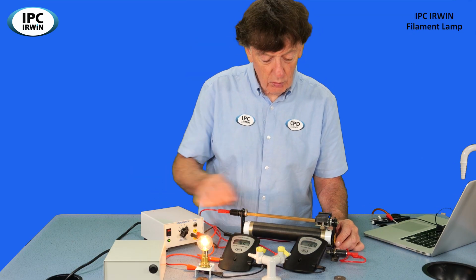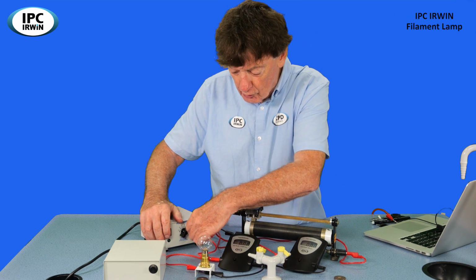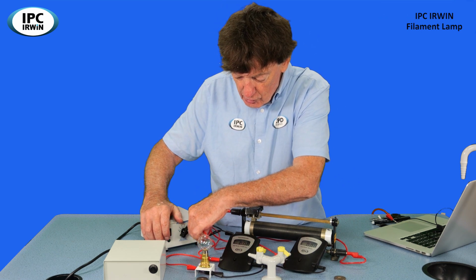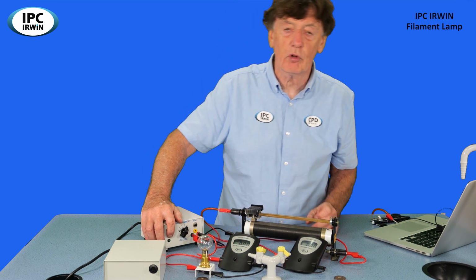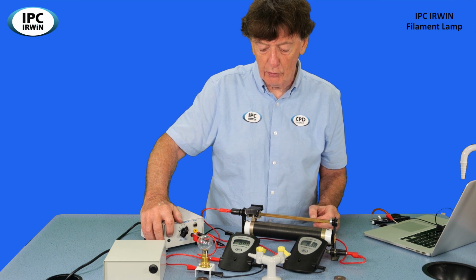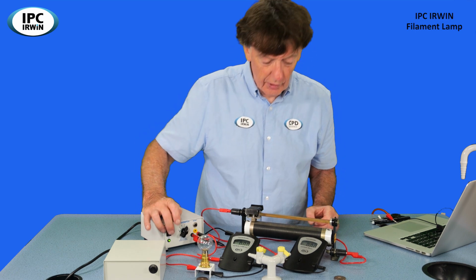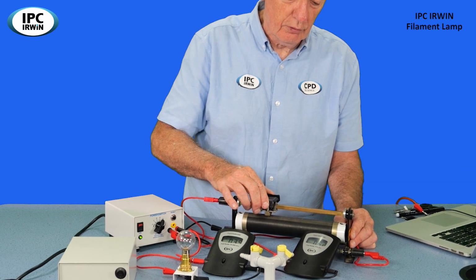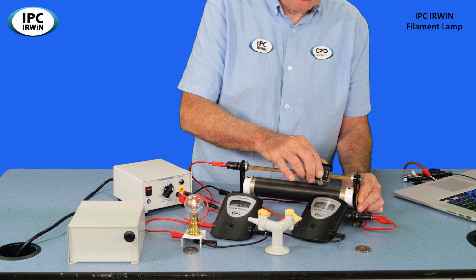What we can then do is go back to 0, switch off, and change over the direction of the potential difference by switching over the terminals there, because we're going to be plotting this graph in 2 quadrants. We'll have negative values of potential difference across the lamp as well as positive. And if we switch on there, we can repeat that for the negative potential difference across the lamp.